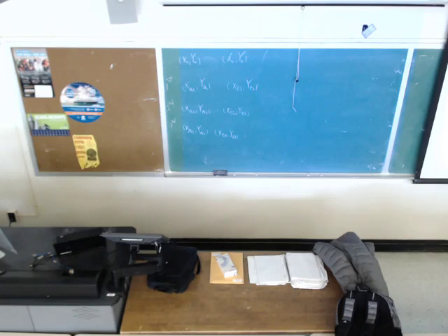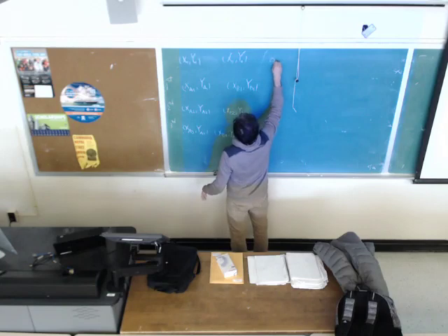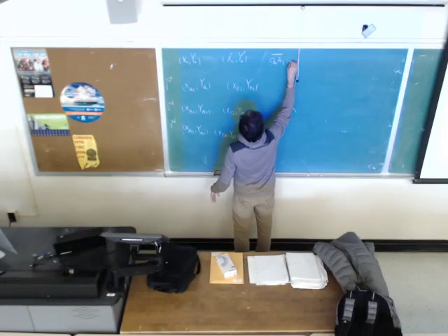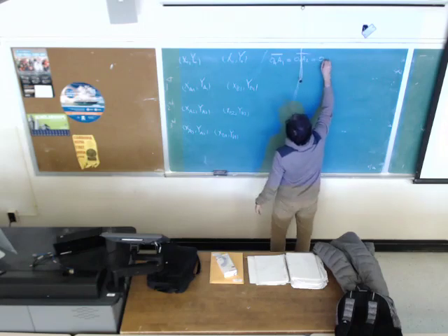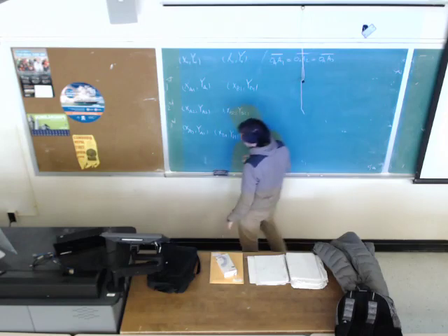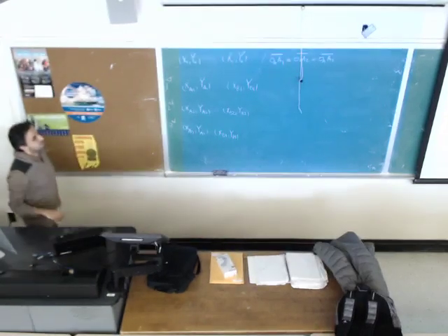If I connect OA to A1, it's going to give me link 2. Link 1 is ground, link 2 is OA A1. When this mechanism is moving from first precision point to the second precision point, OA A1 is going to move to OA A2. And to the third precision point, OA A1 is going to move to OA A3. Saying that, I can say OA A1, the length, is going to be equal to OA A2, equal to OA A3. Make sense?